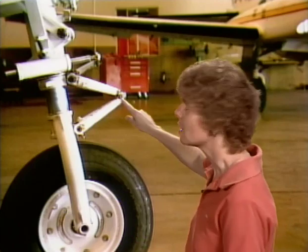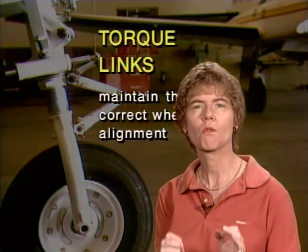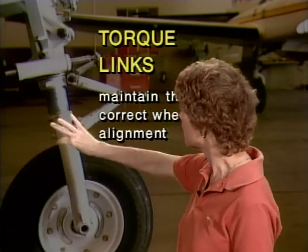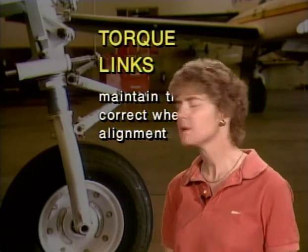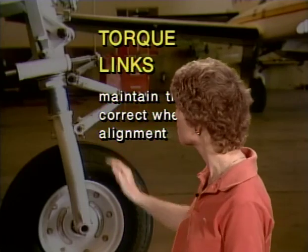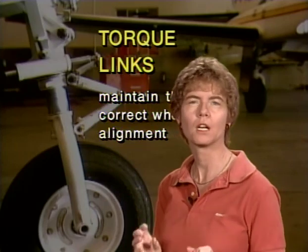Now, when you take a look at a shock strut, one of the things that you'll notice is torque links. The torque links are attached to the cylinder and the piston on the shock strut, and maintain the correct wheel alignment, because otherwise the piston and the cylinder would simply be able to rotate independently, and that tire wouldn't stay lined up the way it's supposed to. So the purpose of the torque links is to maintain the correct wheel alignment.